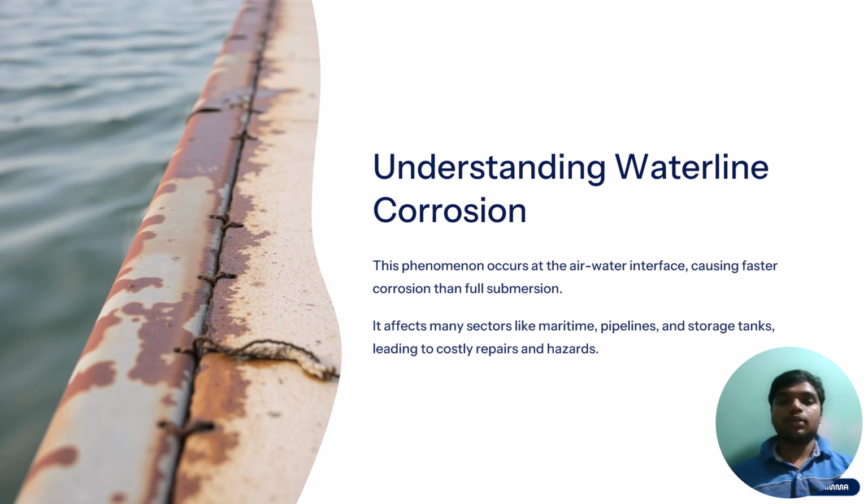Physical factors: high water velocity can cause hydraulic wear, which can strip protective coating from pipes and expose bare metal to corrosive elements. Sediment buildup and poor plumbing practices can also contribute to corrosion by creating stagnant areas where corrosion can thrive.